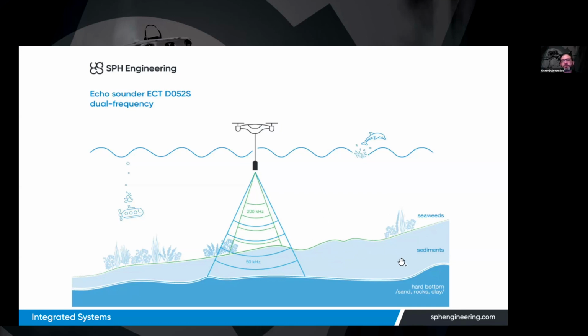But in case of a layer of light sediments, something around few dozens of centimeters maximum, in the data you will see two horizons, reflection from the top of the sediments and a reflection from the hard bottom. So in the single pass, in theory, you can get two measurements till sediments and till hard bottom, and can estimate the volume of sediments.